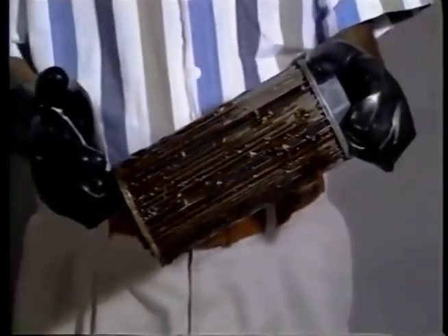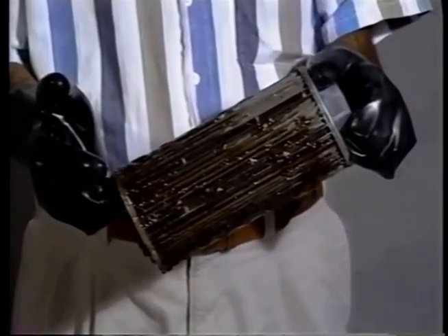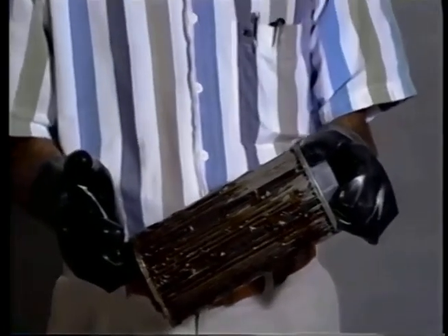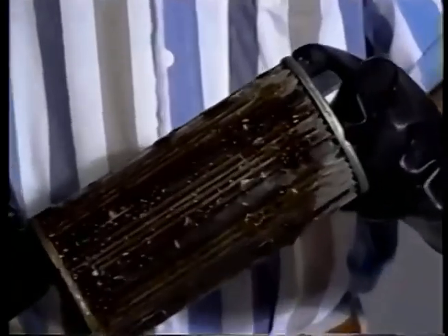Most of the time, bacteria problems are pretty easy to detect. They usually show up first as a slime coating on inlet filters. Bacterial growth also produces a characteristically bad smell. You'll have to clean and flush the system and replace the emulsion to get rid of the bacteria.